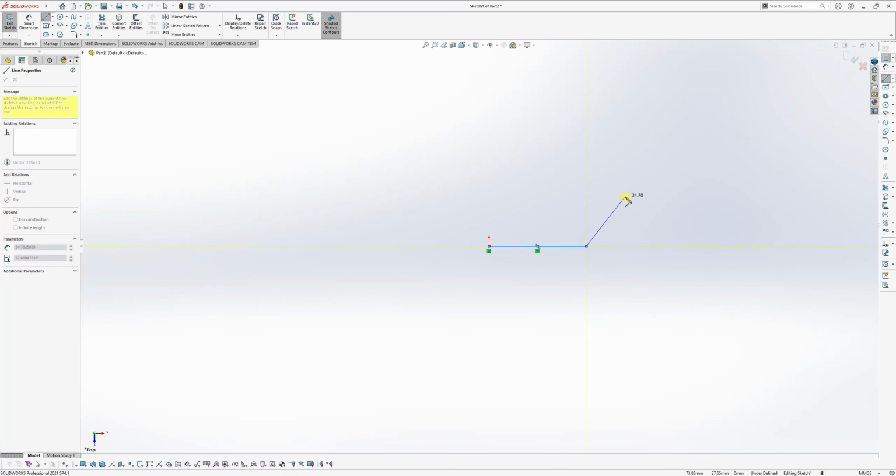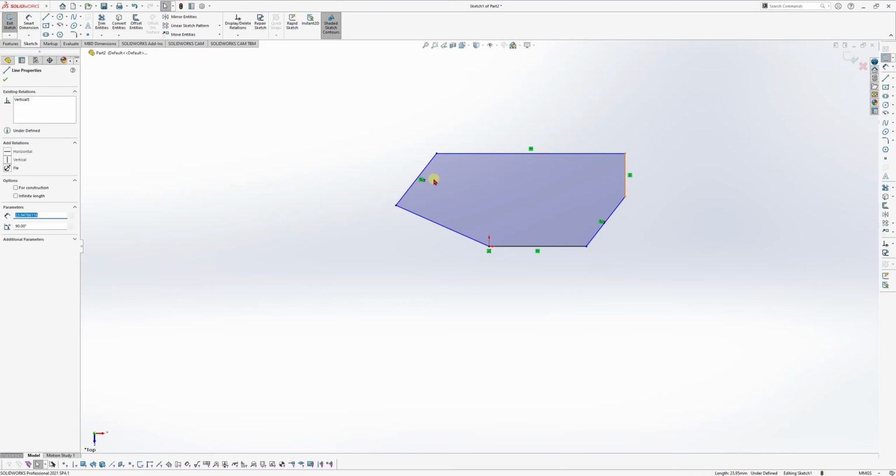Here's the way you put the line. Just click, and then at the end of the line, just click again, and click. Now you created one solid shape. What else is left here is to put in the relationships. So let's say, for example, I want this one and this one to be equal. So I'm going to left click it, and then I'll press Control on the keyboard and left click again on this line, and then all the relationships here will come out.